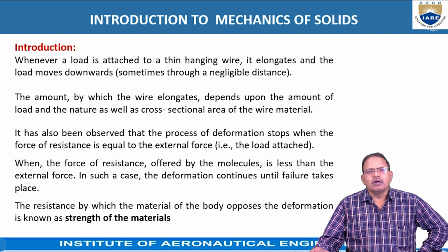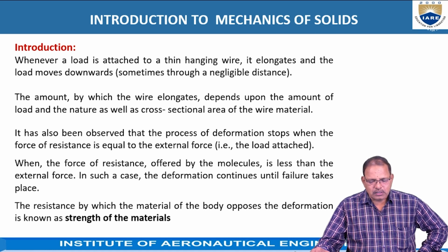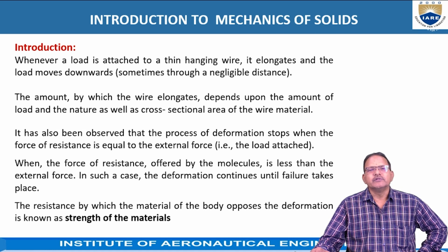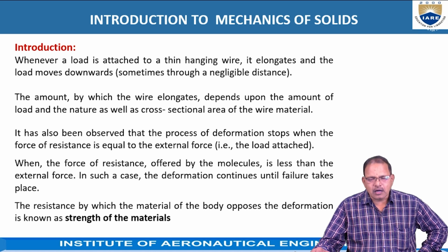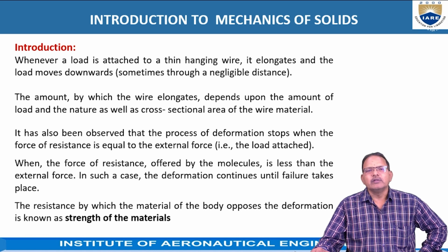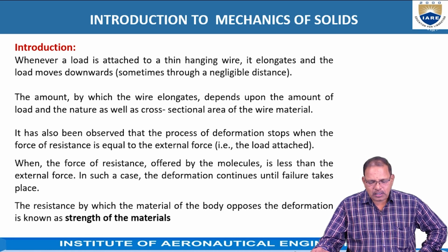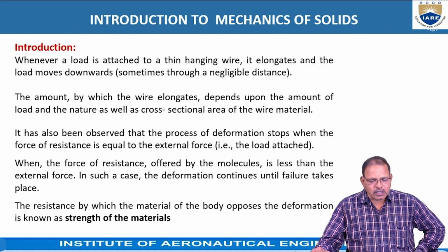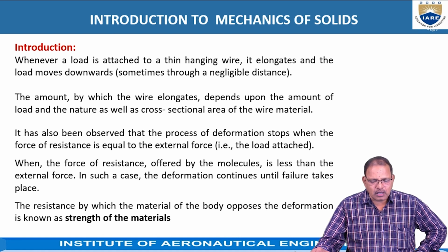But when it is elongating, the internal forces developed by the molecules always oppose the deformation of the wire. When the resistance offered by the molecules and the load attached are equal in magnitude and act in opposite directions, the elongation stops.